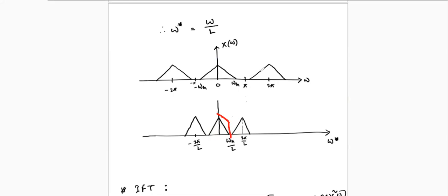If you have done the upsampling, you need to think of the second lobe, whether it is transferred inside your pi. If it is like that, you need to consider the design process of your low pass filter.